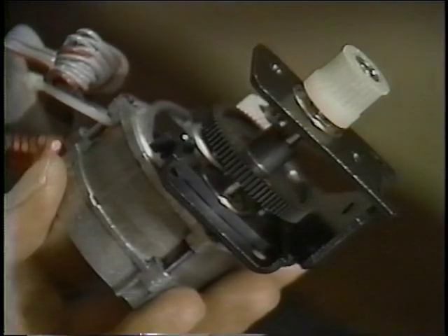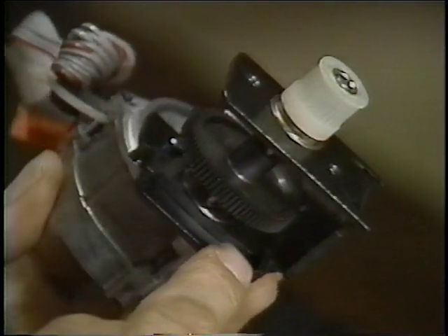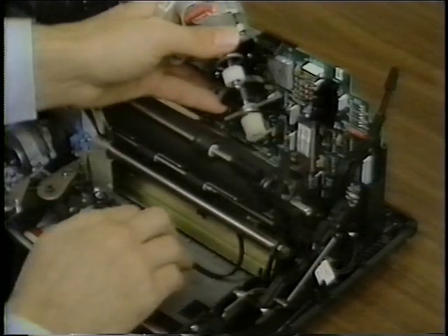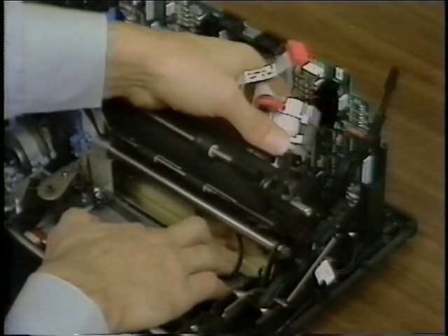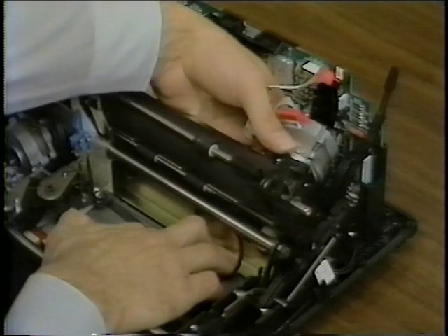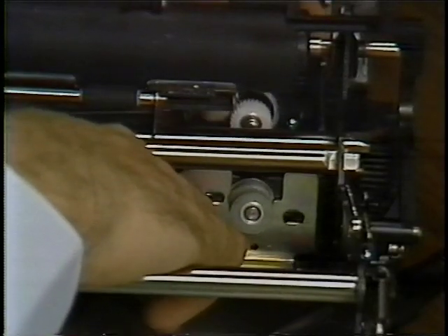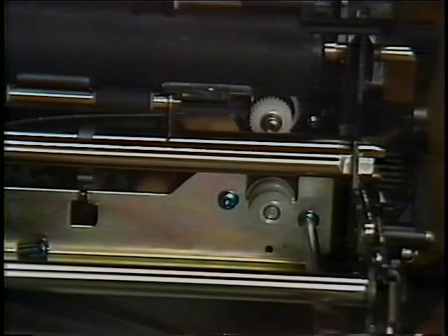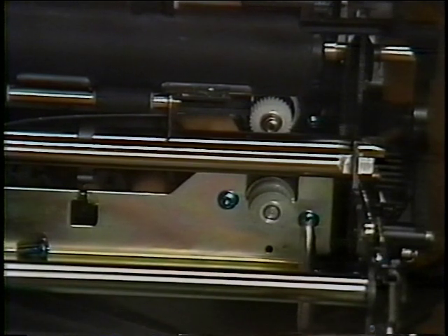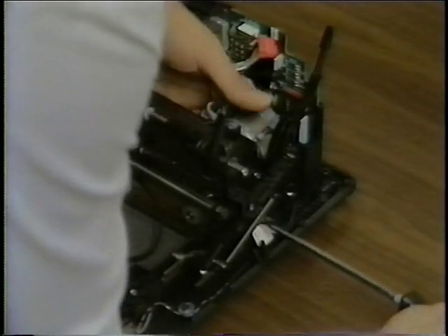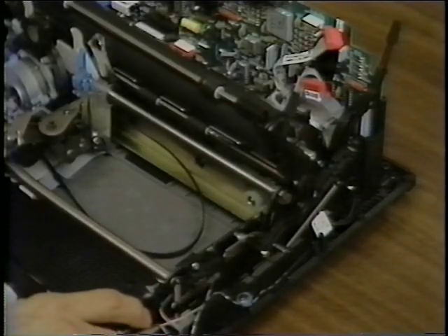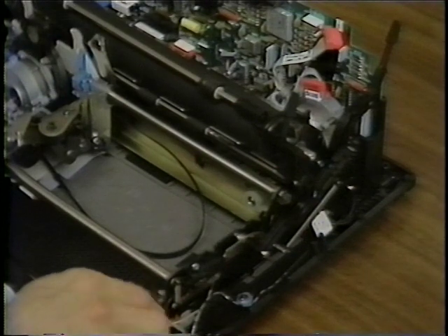The transport shaft tension spring in the transport motor bracket falls out easily. Make sure it is in place before installing the transport motor bracket in the machine. Then work the transport motor bracket into place and install the 4 transport motor bracket mounting screws, but do not tighten them all the way down. Hold the transport motor bracket down and to the front while you tighten the right side mounting screws.